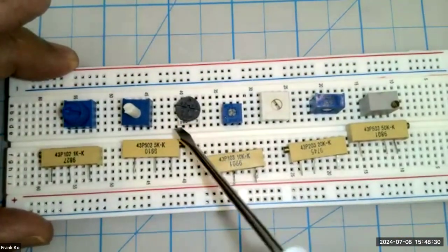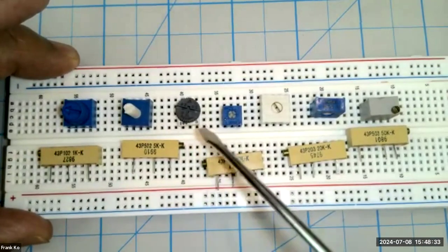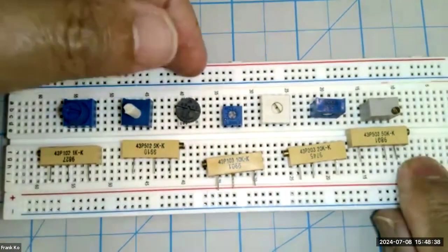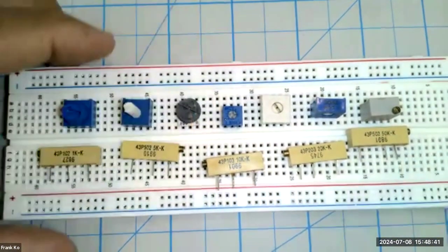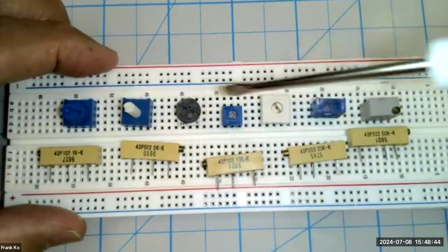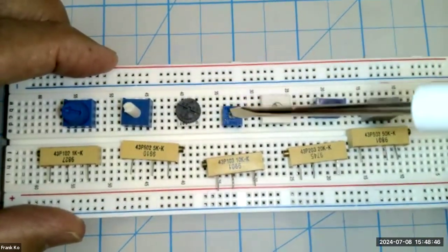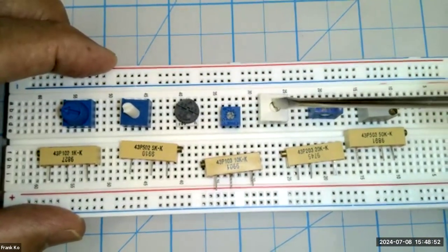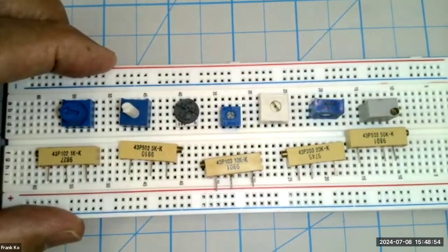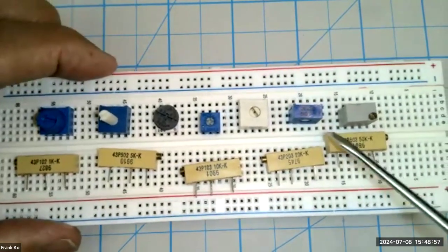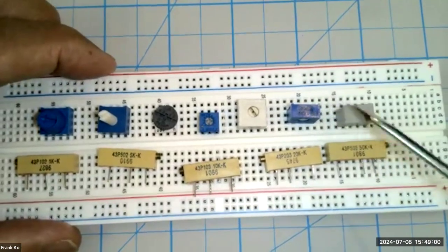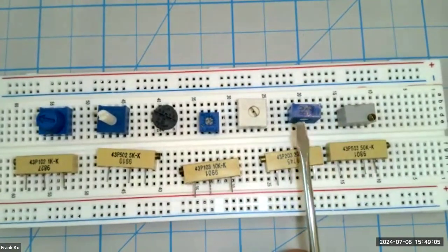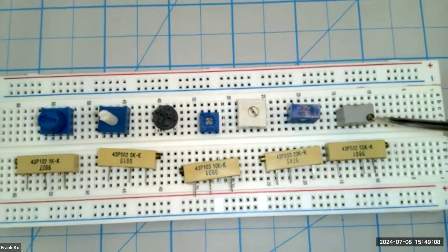It's flat on the board and it shows quite visibly the amount of ohms from maximum that it's capable of. It has a really nice large knob that's flat. Again, I can use my fingers or I can use a screwdriver. The rest of these use screwdrivers. So this one here, this one here. So the physical size of the pot doesn't indicate the amount of ohms. The amount of ohms is determined by what happens inside the pot. And then the last two pots that I have here in the single turn, this one adjusts from the front and this one adjusts with a set screw on the top.